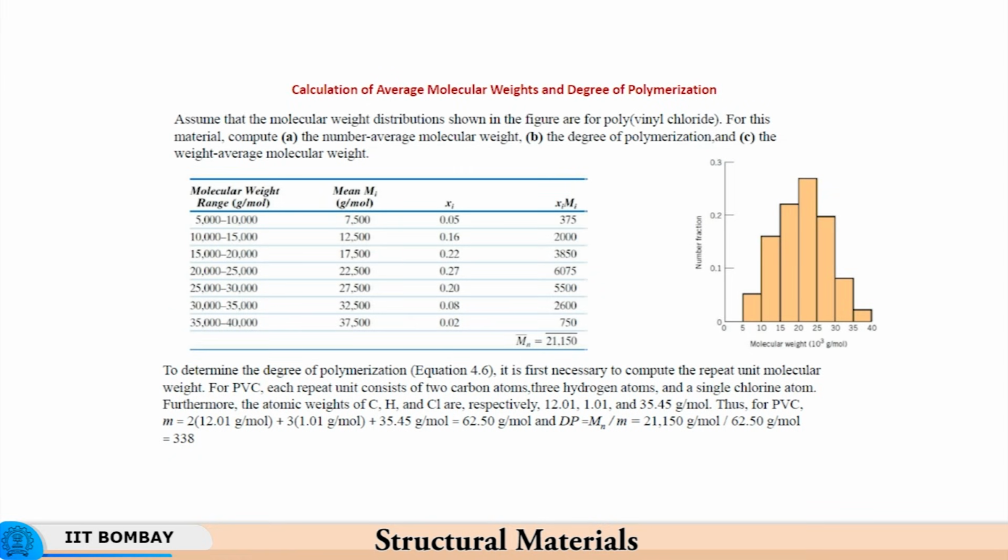So it is of engineering use or engineering application to have a different distribution of weights of different sizes of polymer molecules. So a different extent of polymerization, and a mix of different extents of polymerization in a given sample of raw material, is very useful from a practical point of view. So it's not really a drawback, provided you are able to design your component and the material which is consistent with the strength that you want at the end of the day.